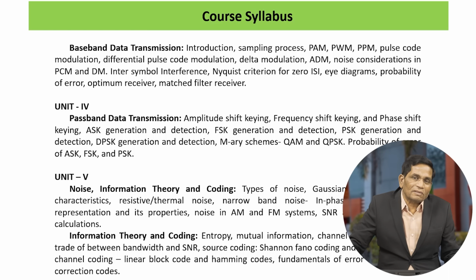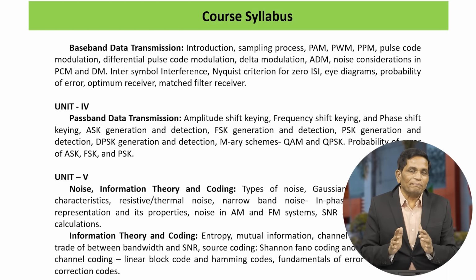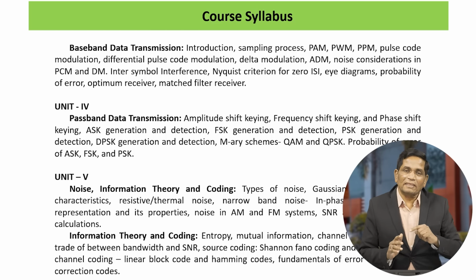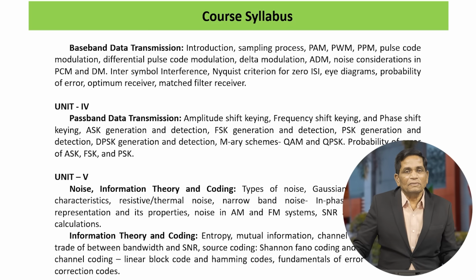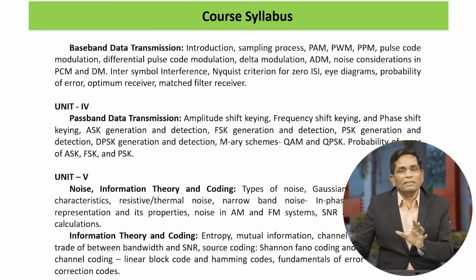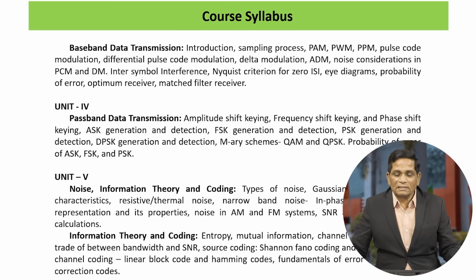Mainly, in order to analyze any digital communication, you should have a thorough knowledge of the sampling theorem. By sampling only, an analog signal is converted into a digital signal. So if you take any block diagram of digital communication, the first block should be a sampler. With the help of a sampler, quantizer and encoder only, we can convert an analog signal into a digital signal.